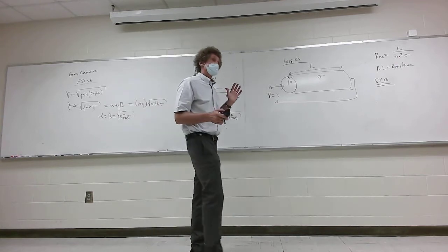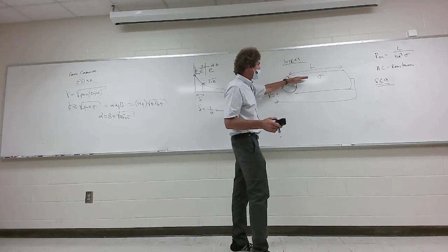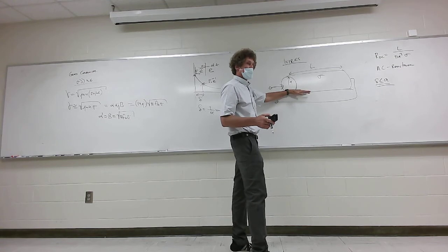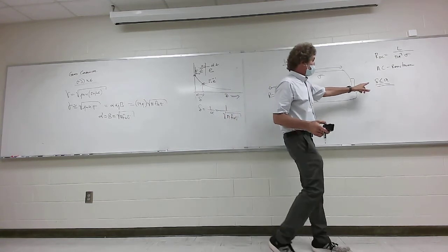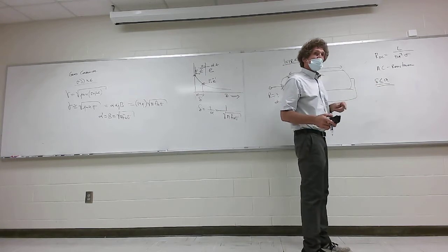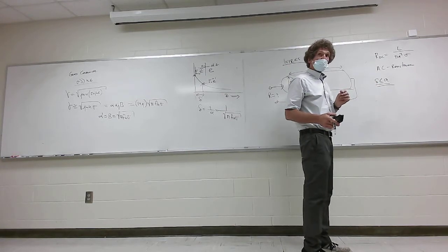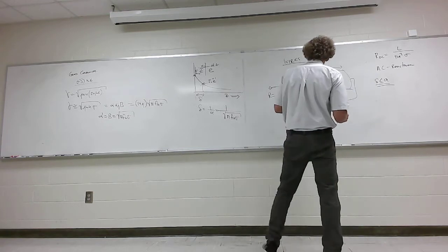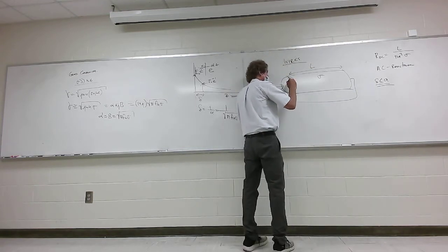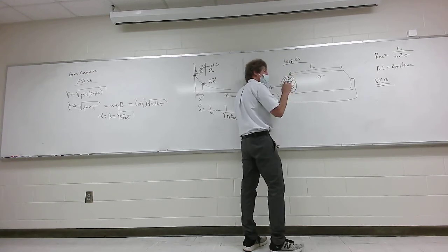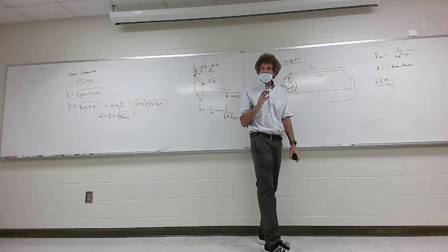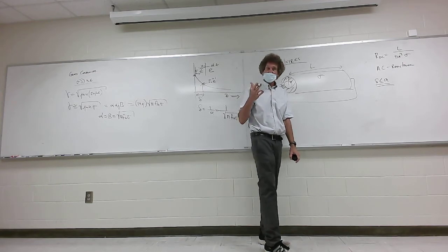Well, I was assuming there was no change in the electric field throughout the wire in the depth as you go towards the center, but there really is. There's a big change if this happens. And all of a sudden, if the skin depth is less than the radius, especially a lot less, then all of the current conducts through the outer layer of the wire. Do y'all follow me? It's not able to get down to the center.